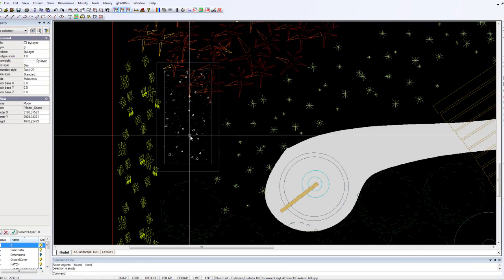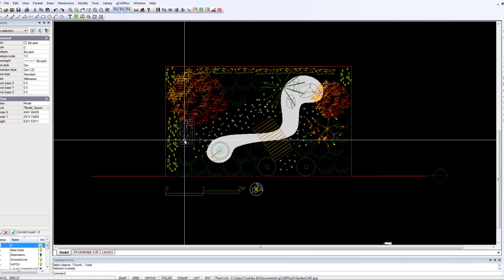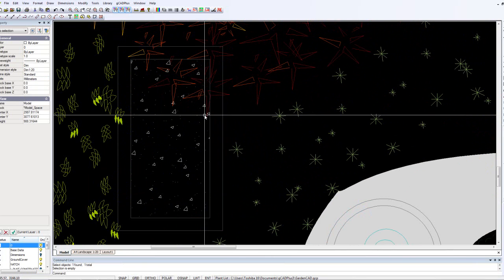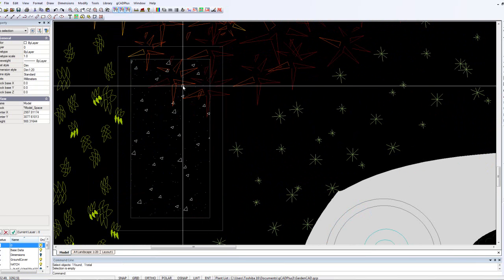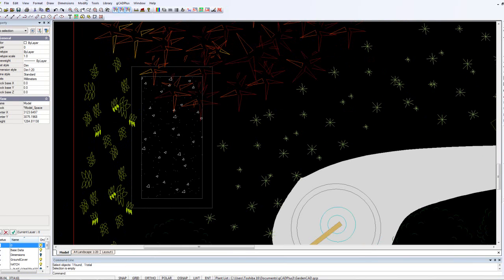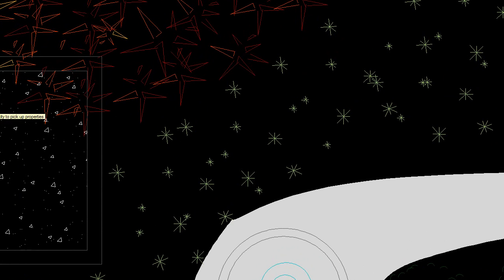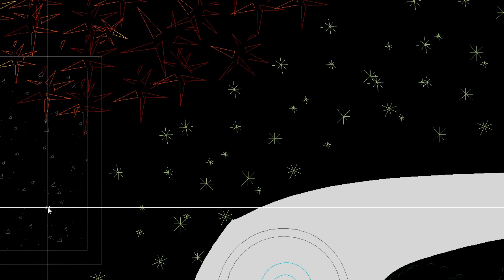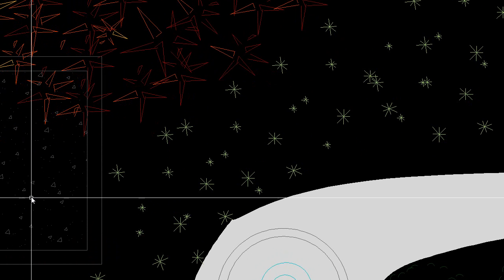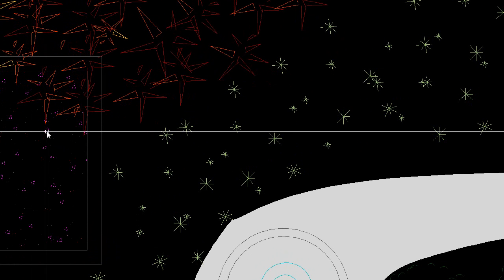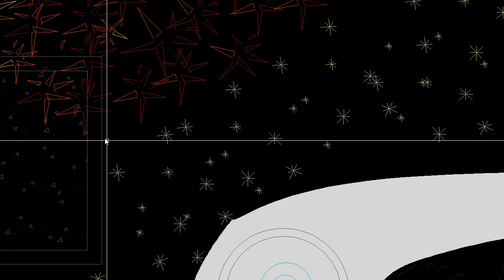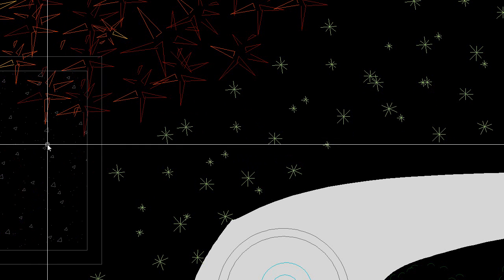We might, and we would probably here, check that that's dense enough, and we should check that it's underneath the little symbol here. We might well take our modify and match properties tool and just match the properties of the hatching to match the color of the background of the frame that holds the hatching. And I'd also be inclined to select it, go tools and send it to the back. So now it's underneath any symbols which overlie it.